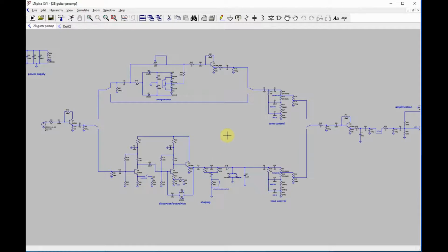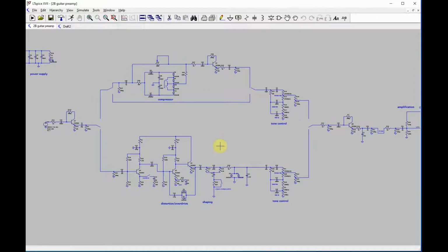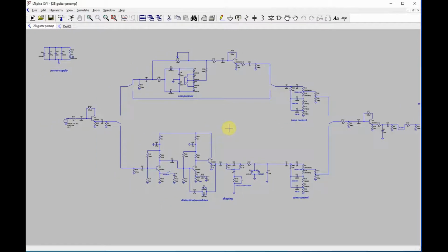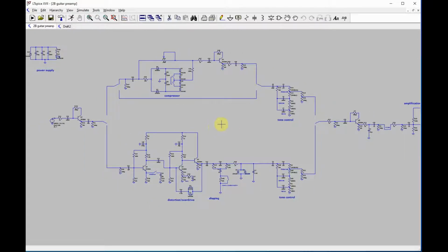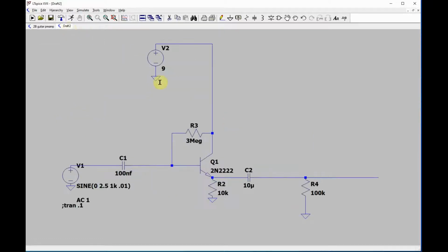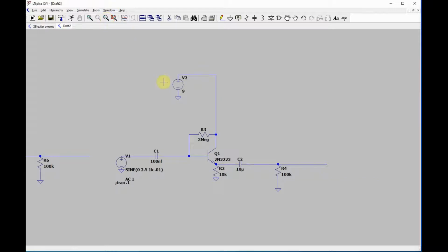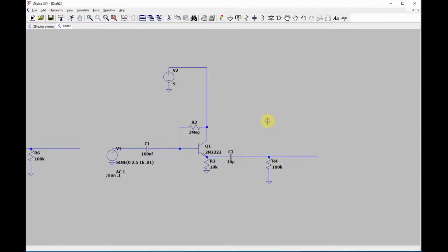Certainly here you're basically never going to exceed the headroom, except maybe initially in this circuit, where you could have really hot pickups and transient clipping, and I guess that could be an issue. But practically speaking, I've checked hundreds of transistors and I almost never get anything lower than 300.